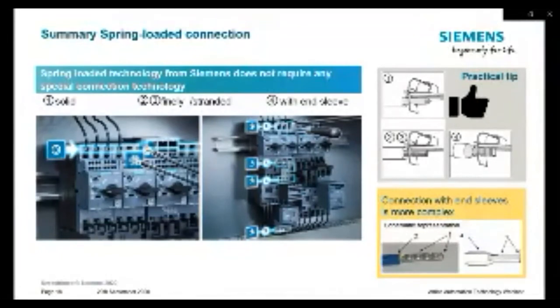But please also consider that connection with end sleeves is more complex. It's not only that you need to do it with the appropriate tools and sufficient strength to press it. It's also the desired length and using the right material for the conductor material you have used.